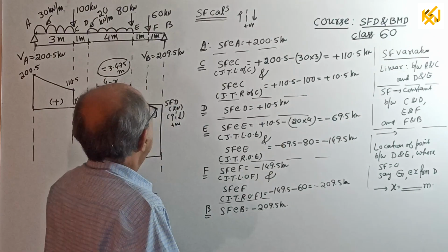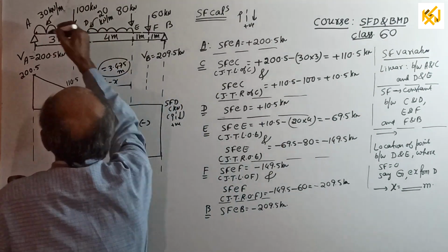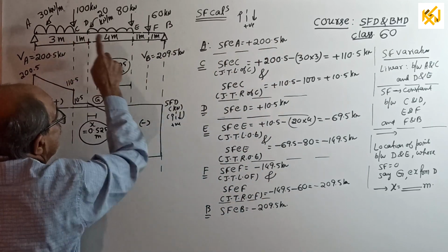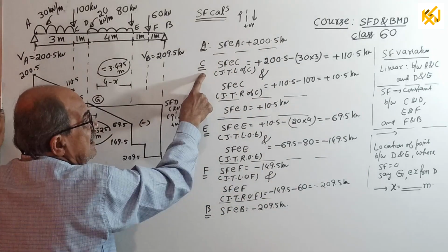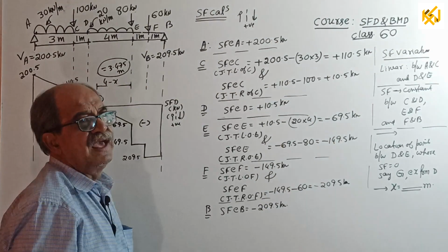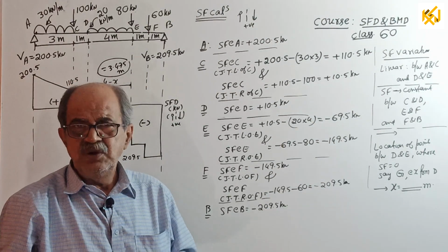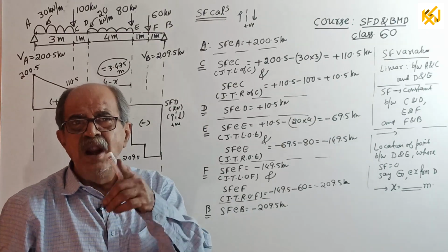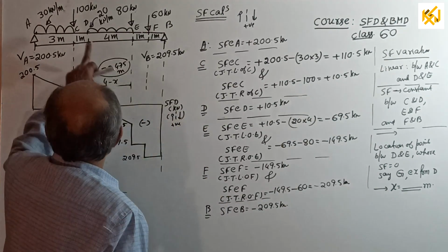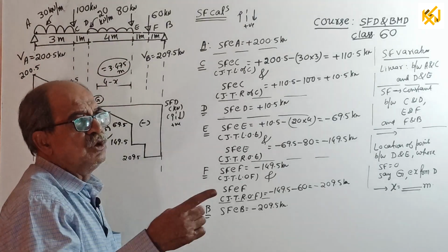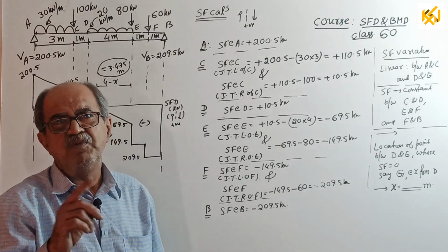Okay, start. Shear force at A, come slightly inside, plus 200.5. Come to C. Now I am not writing like earlier. Note, there is a point load there, shear force you have to do twice. That all I am not telling now because told so many times. See, C point load is there, E point load, F point load. So all those 3 points, you have to do shear force calculation twice.